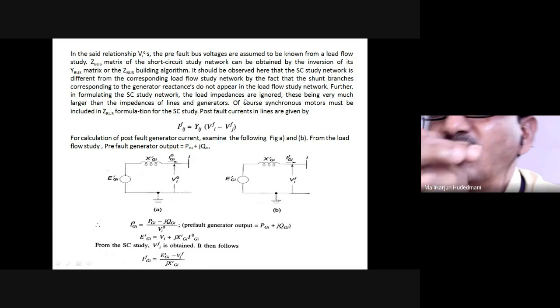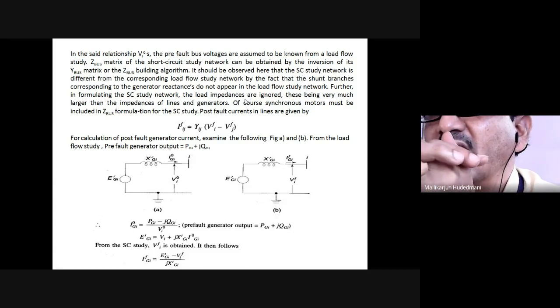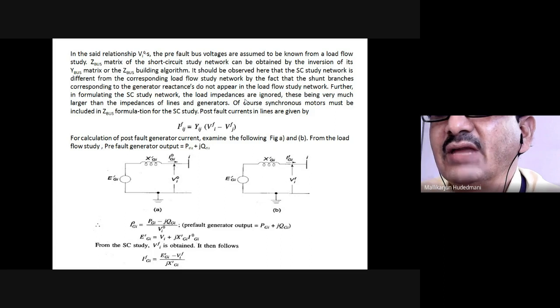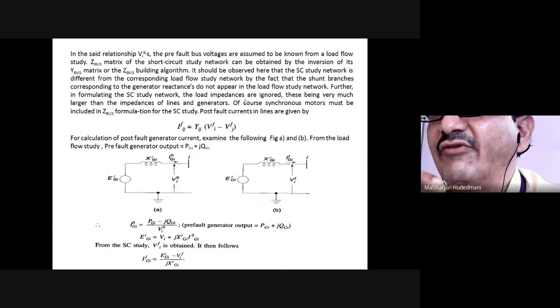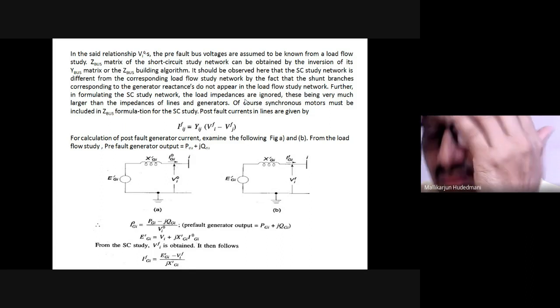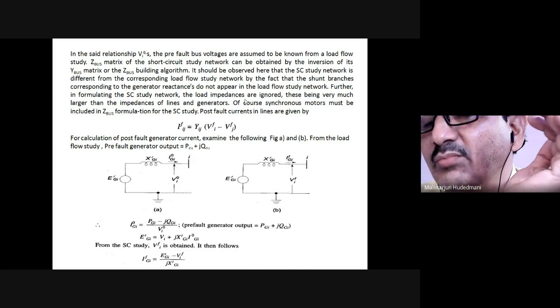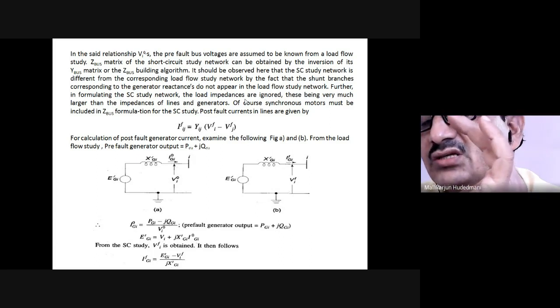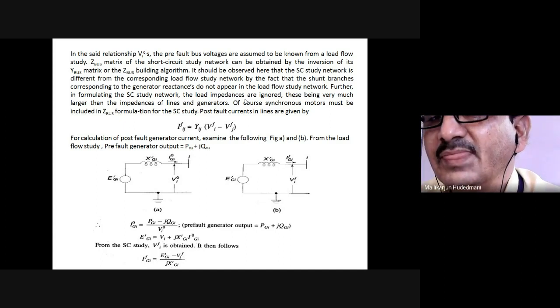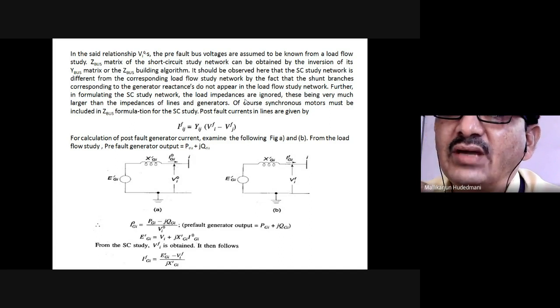As you are aware, we have studied the simple power flow concept. Between two buses, whenever I and J are connected by a Yij, and Vi, Vj are the voltages, I can definitely write the current that can flow during the fault from bus I to bus J as Yij into (Vi fault minus Vj fault). During the occurrence of a fault, the prevailing voltage of bus I is Vi and of bus J is Vj, and the difference in potentials is the reason for the flow of current. Vi of F minus Vj of F, into Yij, gives me the current that can flow from the ith bus to the jth bus.